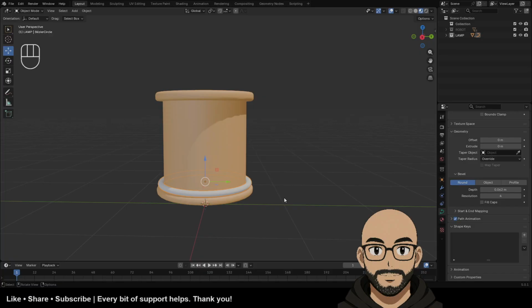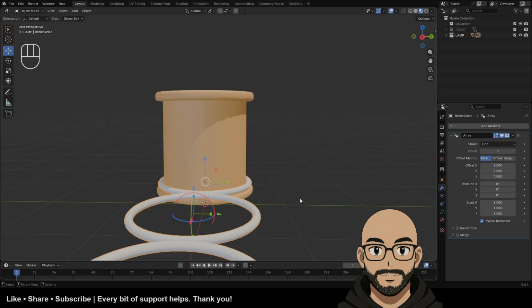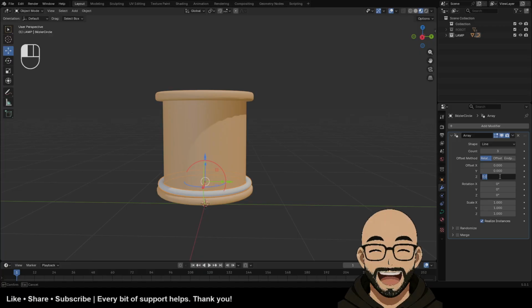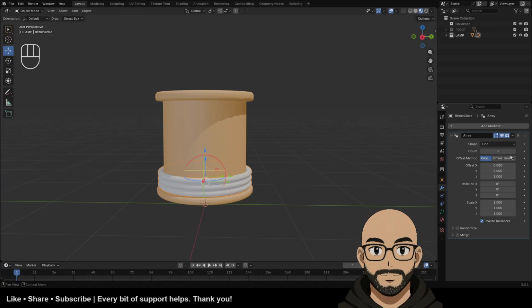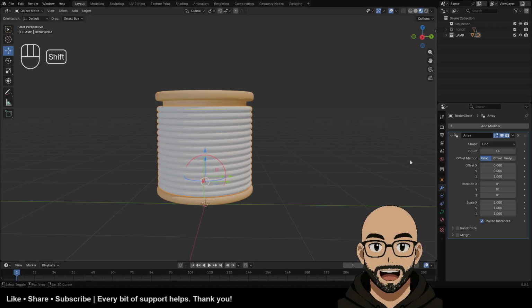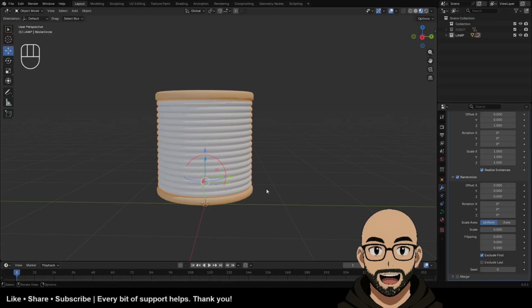Boom. Now we're going to add a modifier, the array. And we know we want to go up in the Z axis because the arrow is pointing up. So we're going to change X to 0 and we're going to change Z to 1. Boom. And there you go, we got wire. I'm going to increase the count so we kind of fill our space. There we go. Now what I want to do is randomize. And I want to randomize some of this rotation.